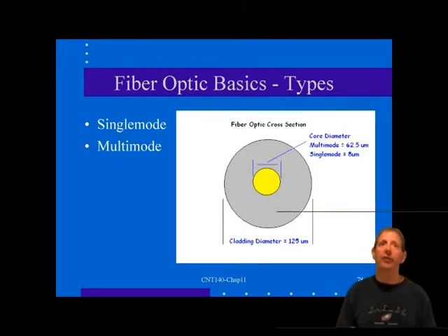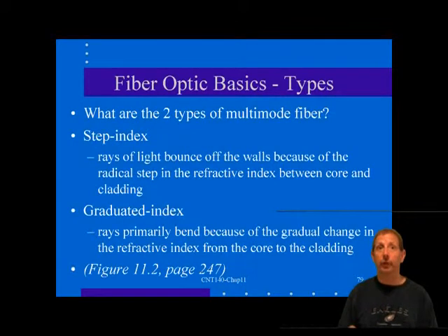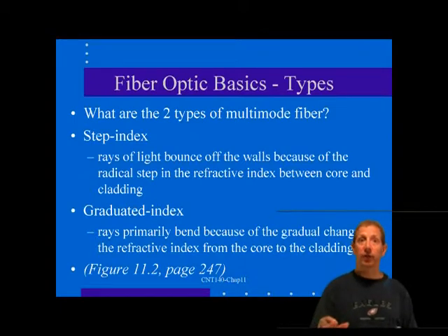The major advantage of loose buffer cable construction is that it takes less time to terminate the same number of fibers than with tight buffer cables. An application with a relatively small number of fibers will not see much difference, but an installation with large numbers of fiber terminations will go much faster with loose buffer construction.